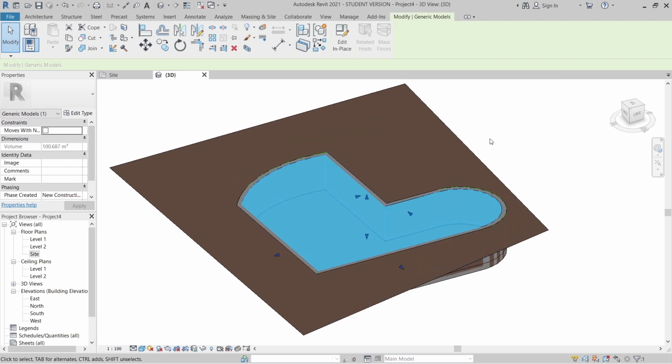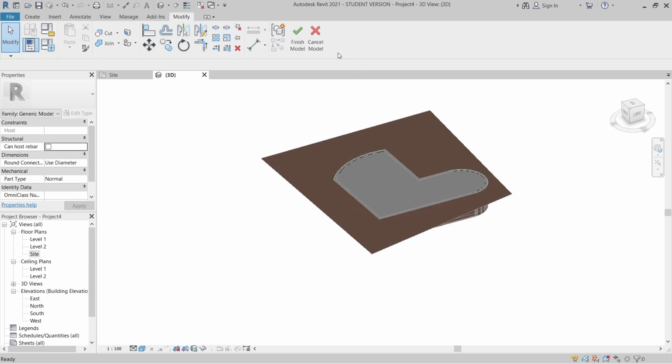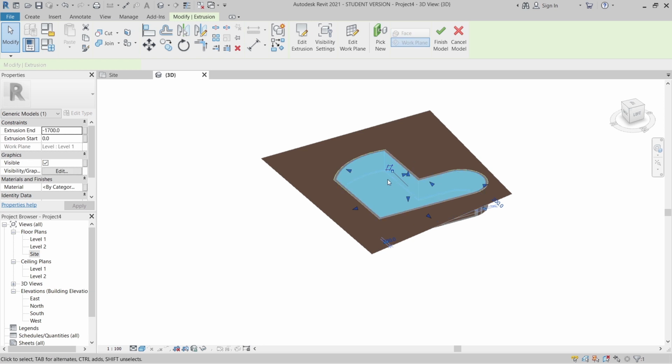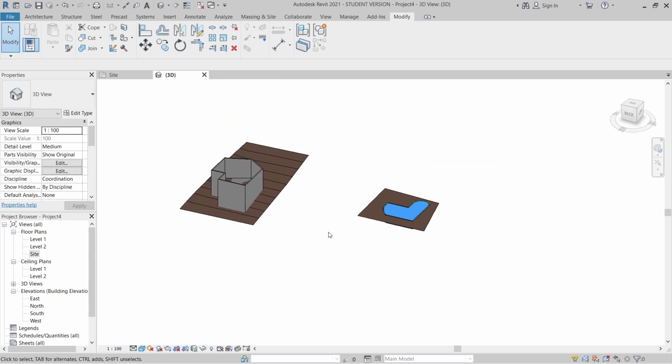But if you want to show your water, you might need to go to Enscape or Lumion or V-Ray to apply this. So in your Enscape or Lumion, you will see your water reflecting properly. In the Revit interface we could not show that, but we make sure we apply the water texture. You can go to your Edit Type, then you can select your extrusion here, then you can apply the material here. Let me hit Cancel first. That's how you can use your building pad more effectively.